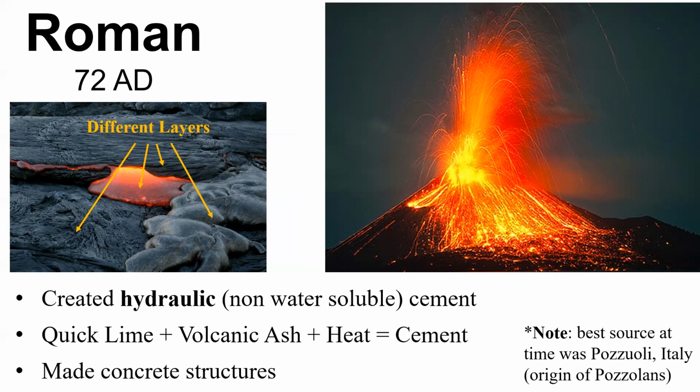It reacts at a much lower rate, and you're able to replace a certain amount of Portland cement with, say, a fly ash. These are commonly at 10 to 30% for fly ash.